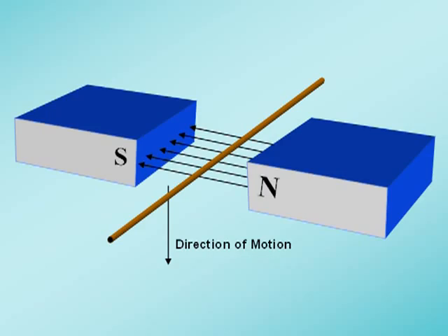Returning to Faraday's experiment, we concluded that current could be induced to flow in a coil surrounding a magnetic material where the magnetic field in that material was changing. More specifically, an electromotive force exists in the coil which causes current to flow. It turns out that we can generate the same electromotive force in the wire by keeping the magnetic field constant and changing the position of the wire.